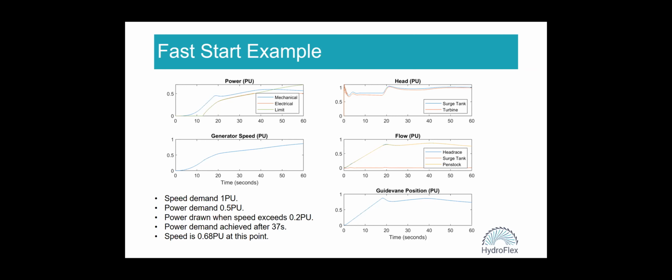Yes, we did a research focusing on stretching the hill chart when utilizing variable speed. On one hand, it's actually possible to stretch the hill chart, but by design, some turbines will allow you to do that, and other turbine designs will actually prevent you from stretching the hill chart, by hydraulic design.